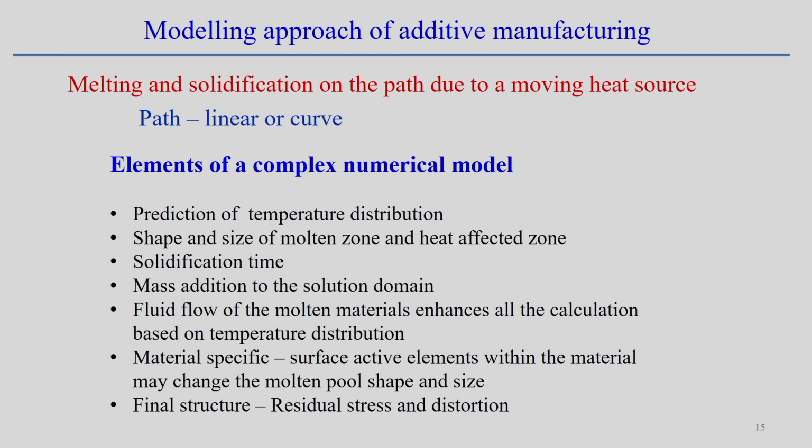So we have to look into the solidification behavior, how to handle the moving heat source, and how to take care of the element activation technique when the heat source is moving or material is depositing over a curved path. These are the important aspects, but what are the different modeling components associated with the additive manufacturing process, for the development of this complex numerical model?